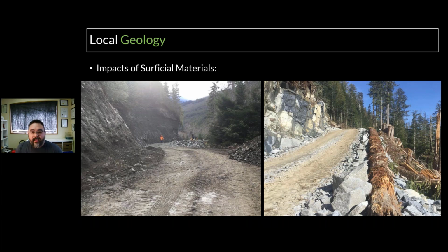If you contrast that with the picture on the right, that's a bedrock road in steep ground again, but full bedrock. So we don't really have any sediment issues, but we still are going to have end haul, so we have to get rid of some of that material. Planning for the sites where it's going to go, or how you're going to stack it, is totally different. You have lots of flexibility with the photo on the right with shot rock. It's well drained, it's stacked steeply, and you can put it closer to water bodies or streams.